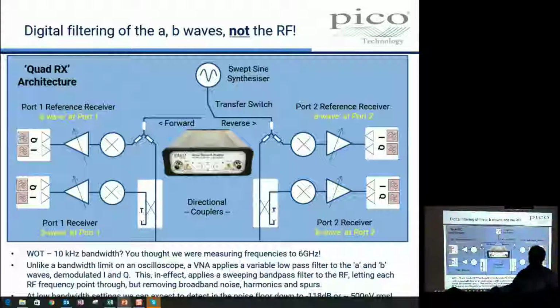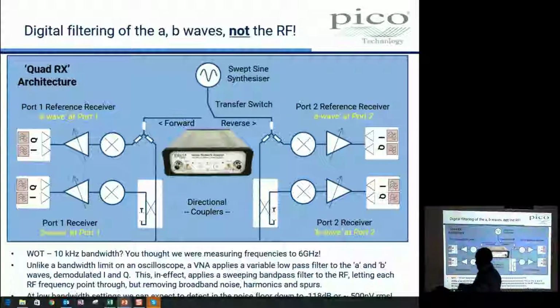All right, so the issue there was that we pushed bandwidth down to 10 hertz from a bandwidth of 10 kilohertz, and we're looking at signals at 6 gigahertz, and this is the concept that I think throws oscilloscope people most easily, because this isn't an oscilloscope. This is a frequency domain product, and it has a very, very important part in its architecture: the mixer.